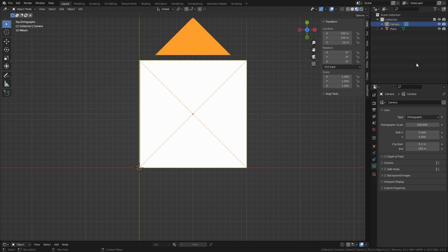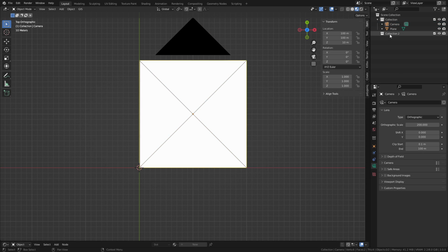All right, at this point in time, very important, if you have other objects, very good idea, put them in a new collection, like my track objects or track objects. And when you have your other objects in this collection, you want to turn them off in a render. You do not want them rendering. You just want your height map rendering. So you're going to turn those off.